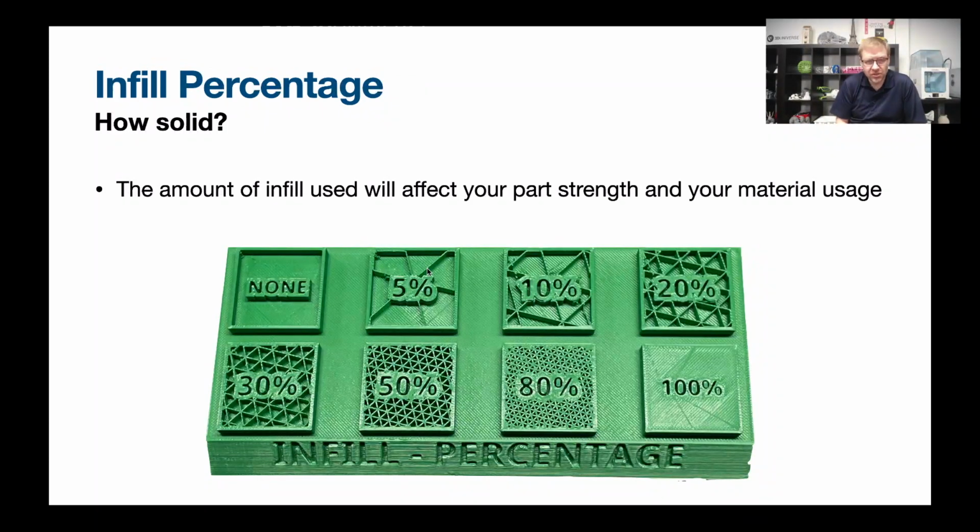But then it also impacts your strength a great deal. If this is a part that's going to be under some stresses, I would say you want to be at least in the 20 to 30% range and probably somewhat higher. For a part that's really going to need to hold up some stresses, I would say you want to be in the 30 to 50% range.